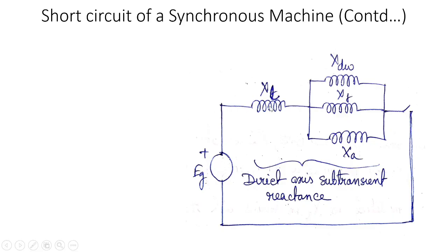So XL is limiting the short circuit current that flows in case of a fault. Here we have a switch. If we close the switch, it will represent a symmetrical short circuit fault, which involves all three phases. This is a single line diagram which represents all three phases, and as it is a symmetrical fault, the conditions are similar in all three phases. So if I study only one phase, I can safely say that the other two phases are going through the same reaction,